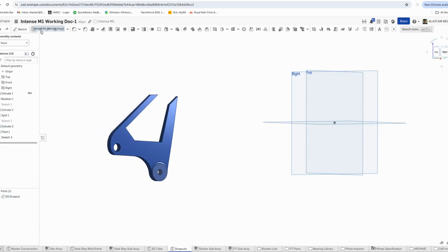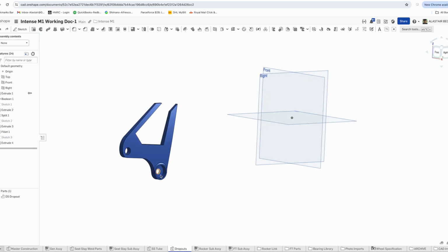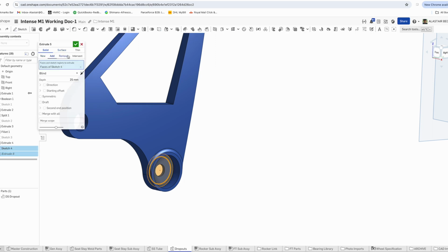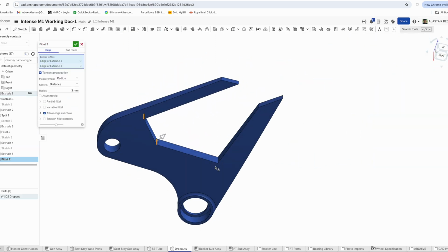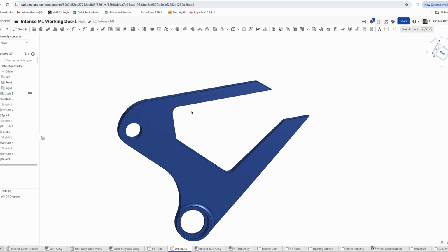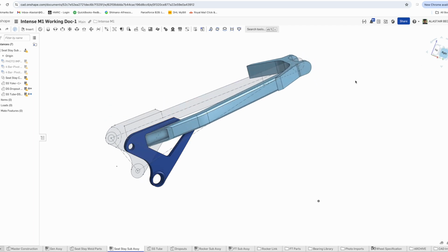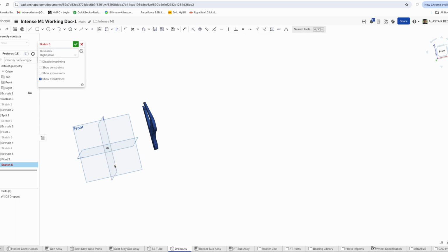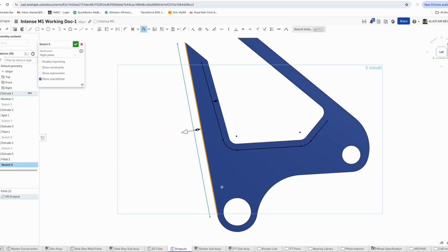Okay, now I'm just putting the recess for the bearing into this part. Now we've modified the thicknesses of it all, so we're going to make a 7 or 8mm bore for this bearing to go into, and then cut a relief at the back as well. And then that should get this part pretty much finished, and then we can update that sub-assembly and make sure everything looks correct. And again, we'll stick some little rods on here to try and soften the whole part. And yeah, it looks pretty good. We obviously ignore that there's no mech hanger, there's no brake mounts on this, but you could spend a little bit more time and model those in if you wanted to be super accurate.